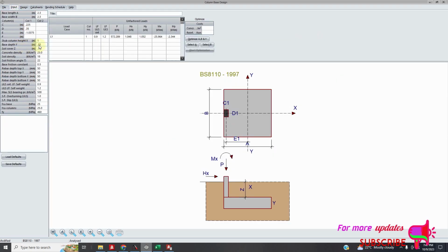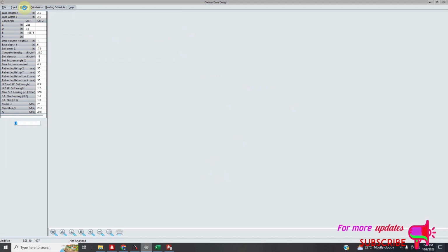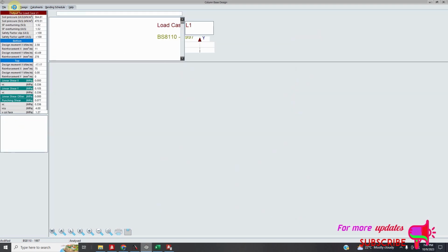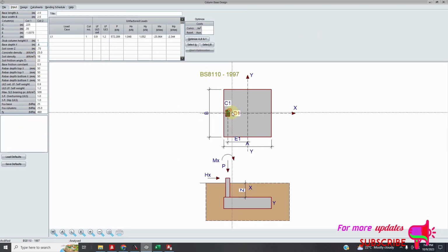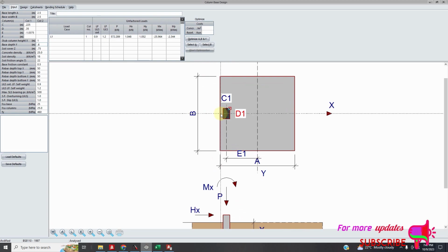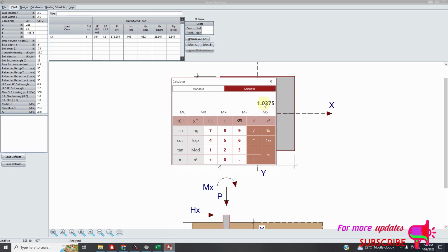So depth is this depth. So let me increase this one to now 0.25. 0.25. Then this one should be 0.6. We first check. Okay, it's passing, but now I want this to be right here on the very edge. So 2.5 divided by 2 is 1.25.